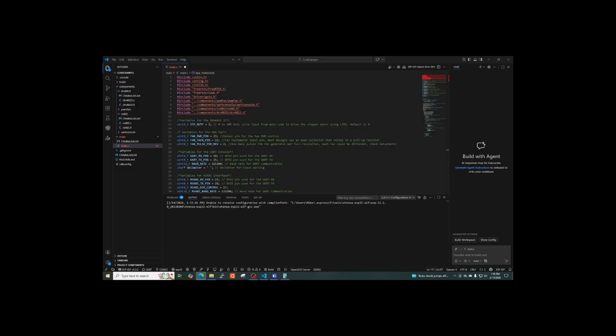All right, so let's see, about 10,000 cycles per memory store. So what we could do is set it up so that if the counter is divisible by like 20 or 10 or something, then go ahead and write. That way we could reduce the amount of write cycles to the non-volatile storage.